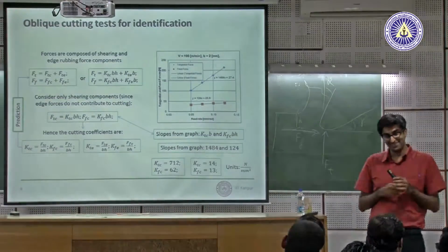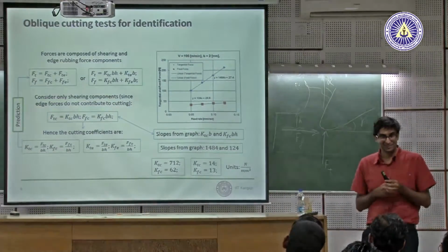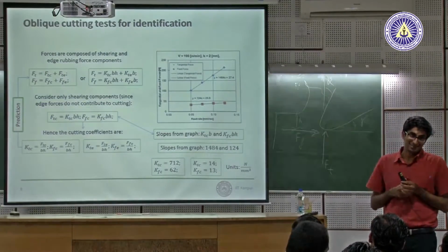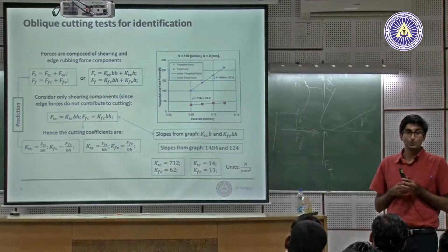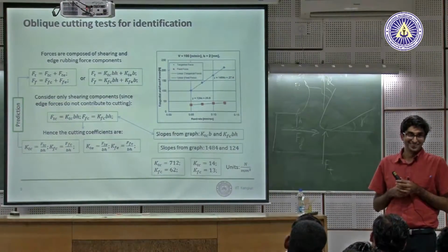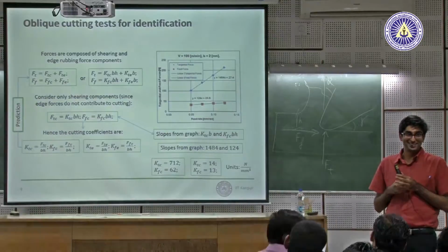So, suppose I have a 25 mm diameter, and I want to make it 24.8. So it will be 0.1 mm depth of cut. Speed is different from depth of cut. So what is width of cut in that case? What is width of cut?